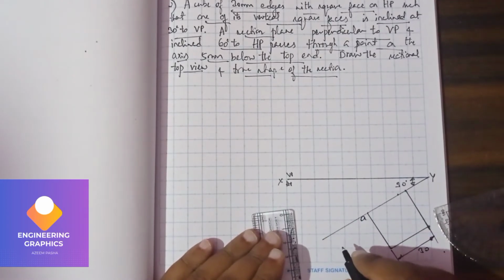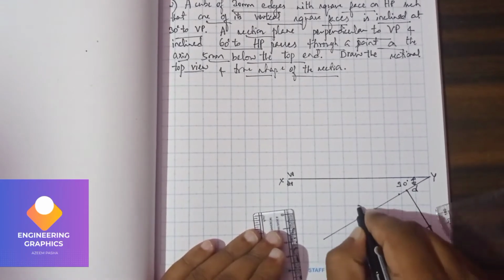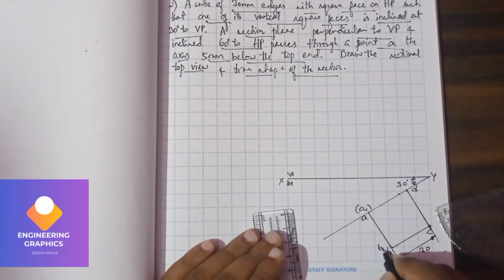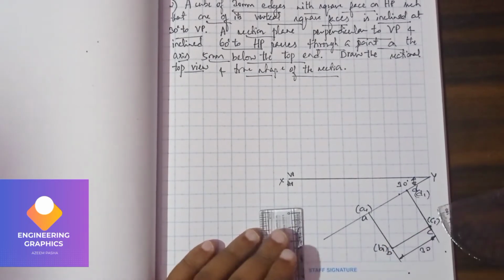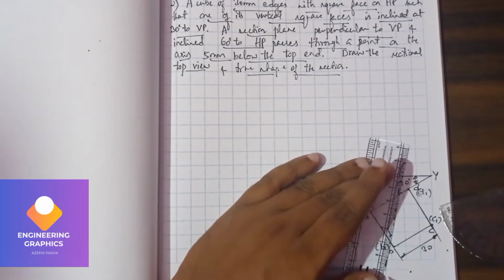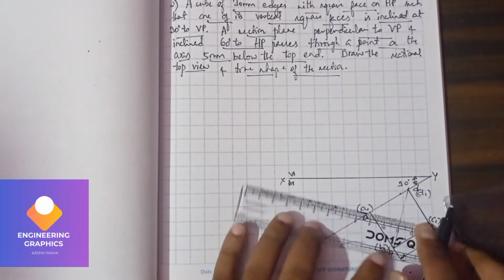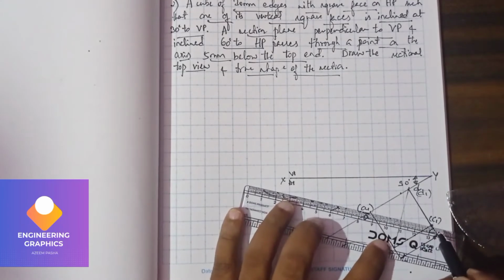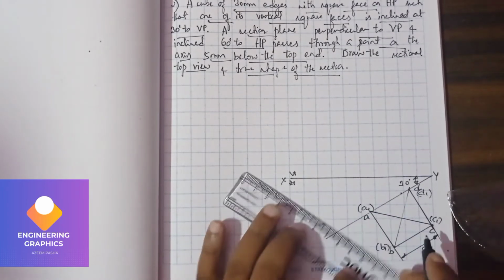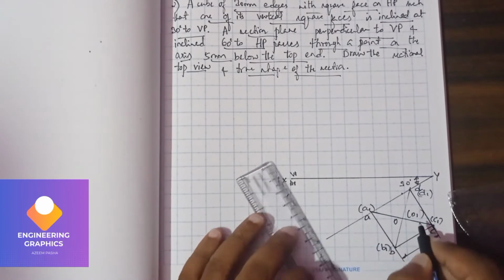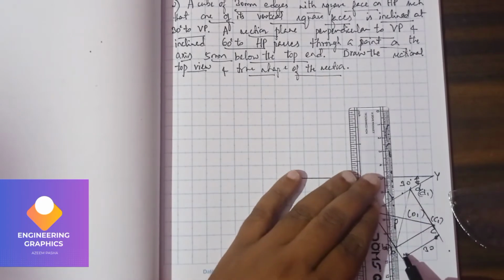Here I'm going to give the namings: top face A, B, C, D, and for the bottom face A1, B1, C1 and D1. All these are written within brackets because the bottom face is not visible from the top view. Draw a thin line to connect and find the midpoint of the axis, that is O and O1. Now project the lines upward to draw the front view.